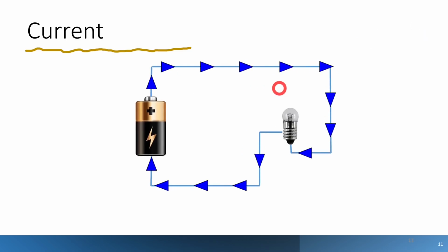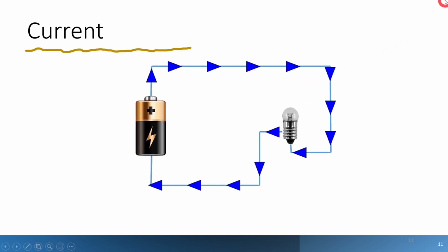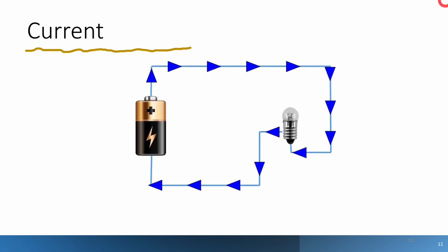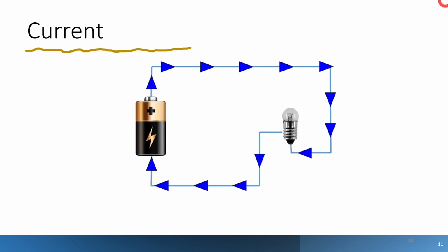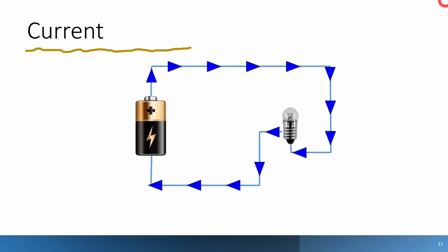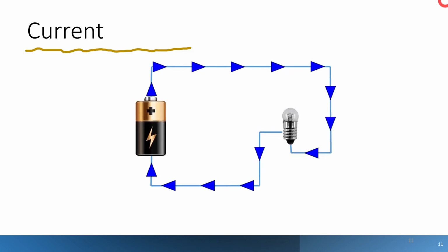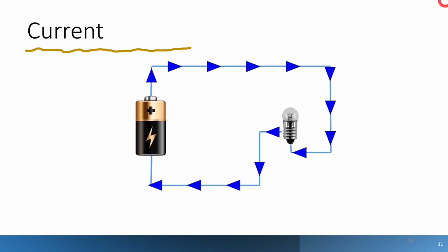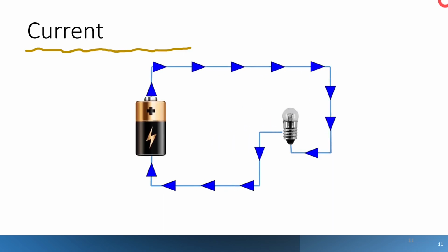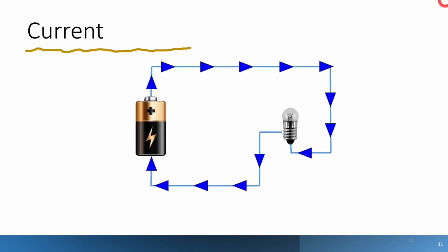And physically, it'll make a lot more sense when we get into more electrical symbols. The electrical symbols, which came about at these conventions as well, use arrows quite often to show where the current is flowing, and the arrows are pointing in the direction of conventional current flow. Fluke meters put arrows on the amp clamps, and that amp clamp is pointing in the direction of conventional current flow. So there's a lot of reasons that I have to study that. But the main thing is when you're out in the field, people are always going to be talking about current going from the positive to the negative terminal of the battery.